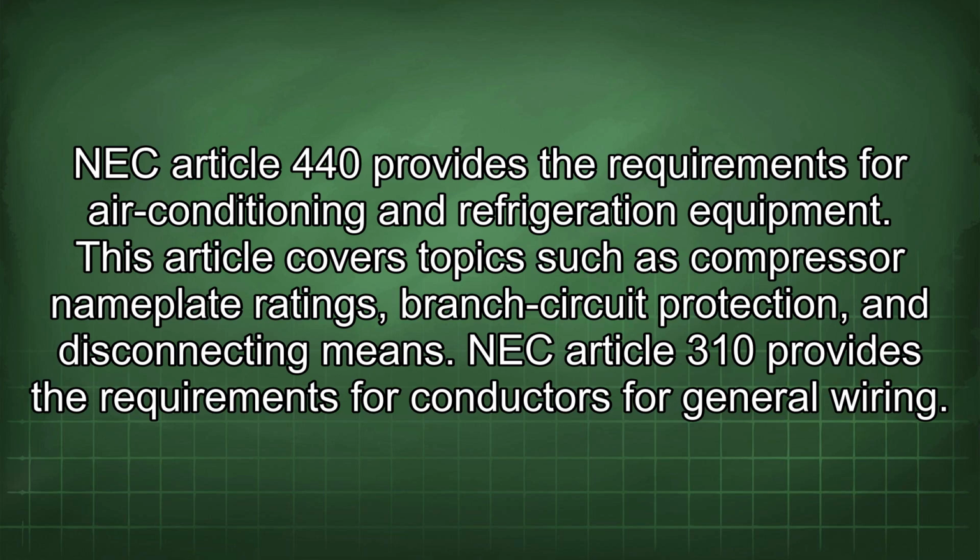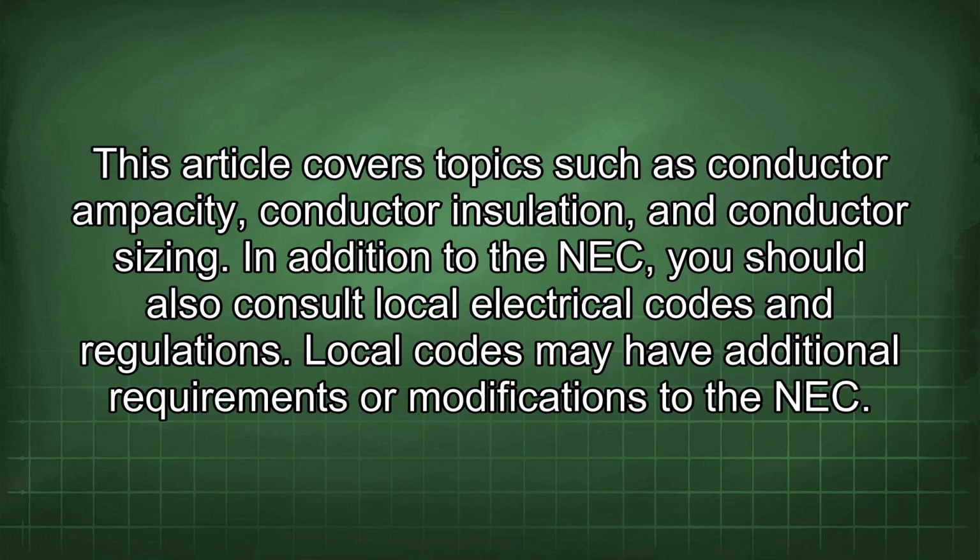NEC Article 440 provides the requirements for air conditioning and refrigeration equipment. This article covers topics such as compressor nameplate ratings, branch circuit protection, and disconnecting means. NEC Article 310 provides the requirements for conductors for general wiring. This article covers topics such as conductor ampacity, conductor insulation, and conductor sizing.